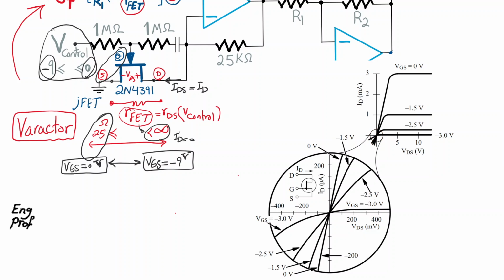If we zoom in into that area, we get to this large circle in which you can see the N-channel JFET, or Junction Field Effect Transistor, shown with the drain, gate, source. And then we are saying that when VGS is 0, which is the maximum value we can consider, the current versus voltage line has the highest slope, which means the lowest amount of resistance, like 25 ohm, 30 ohm.